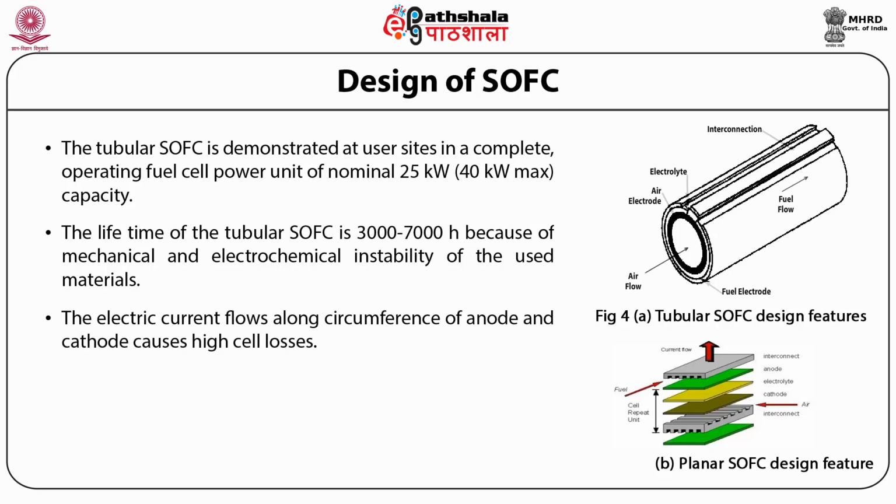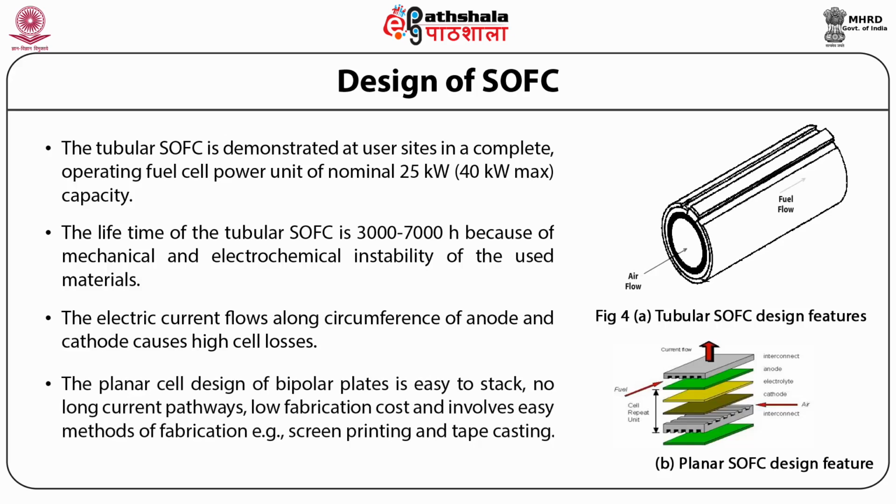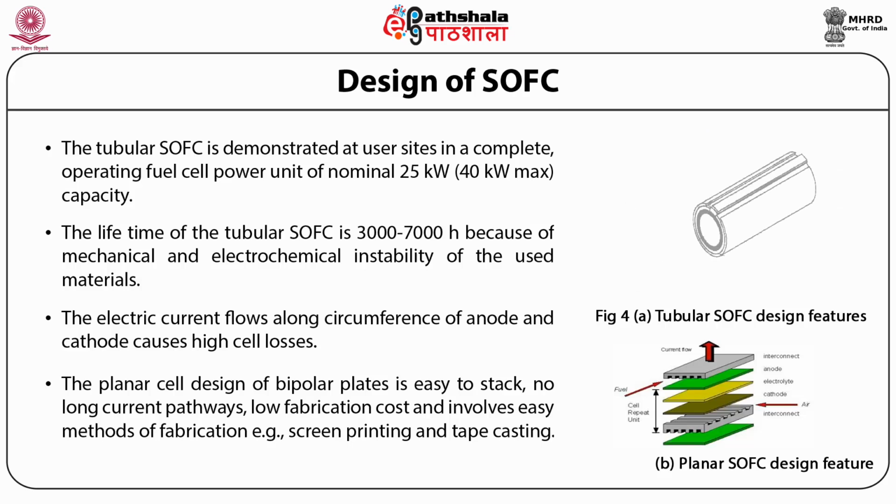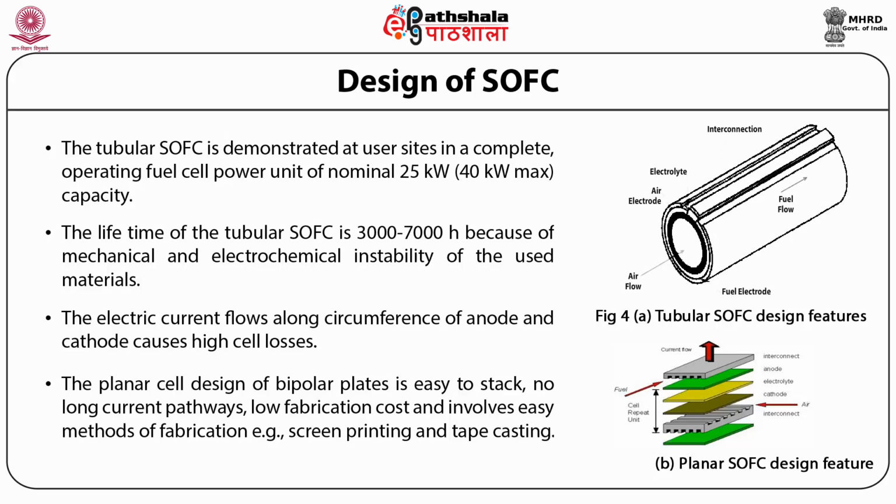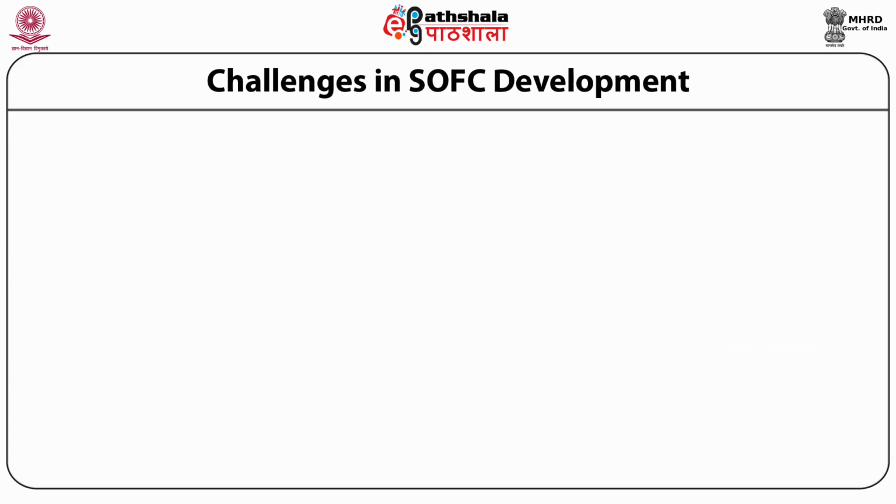Another type of SOFC design is the planar SOFC design. The planar cell design of bipolar plates is easy to stack, has no long current pathways, has low fabrication cost, and involves easy methods of fabrication, for example screen printing and tape casting. The drawback in the planar design is thermal expansion mismatch between ceramic and support structure, leading to problems with the gas sealing.